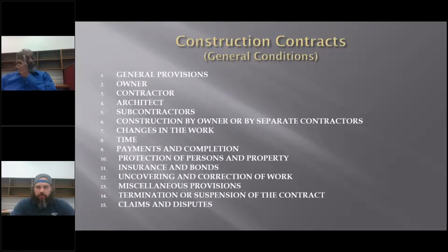The time and duration of the project, how payments are handled, payments and completion, and that can kind of relate to schedule as well. Is there any retainage going to be held on the project? A lot of projects have either a 5 or 10% retainage that's held out by the owner until the project is complete.